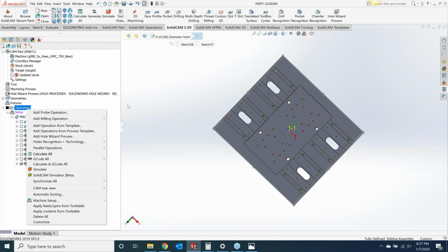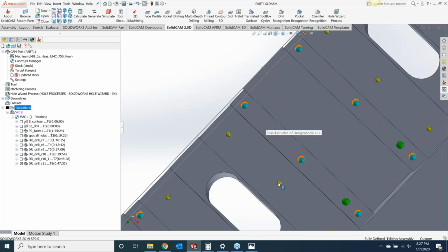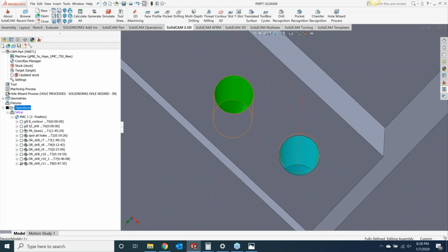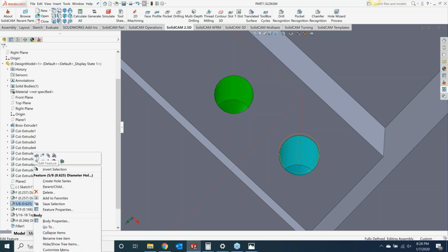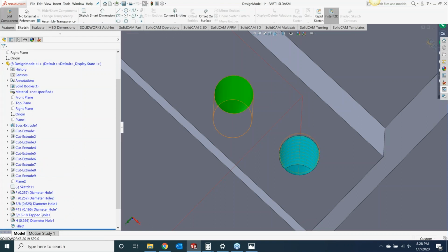Yeah, so in SolidWorks, you do have the option to fully show all the threads, or you can just show it as right here. This one is not showing any cosmetics or anything, and that's all based off of the solid model itself. So if I go to my solid model, we'll go ahead and edit that feature. Actually, it's this one right here. 1618, edit the feature.